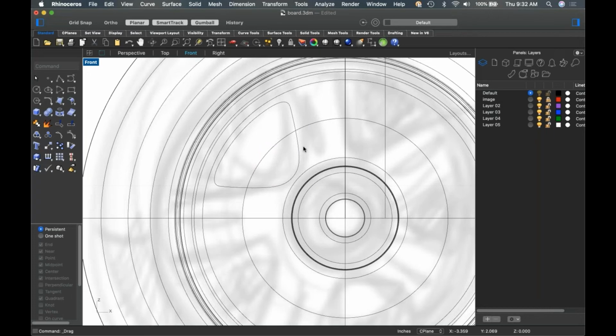So if I just blow a hole through this thing, I have to keep in mind that when I put a fillet on it, the opening is actually going to be a little bit bigger, right? Because the fillet is going to cut back into the surface a little bit like that, right? So I have to plan for that.